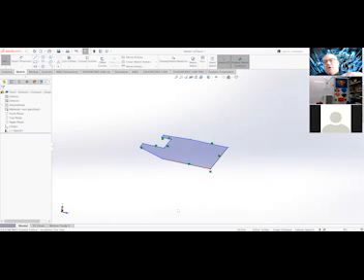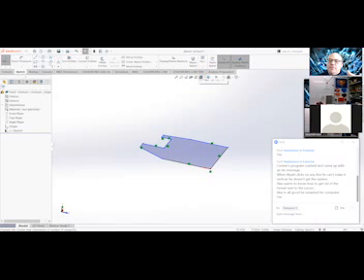So fixing your drawing is one of those things that we don't anticipate needing to do until we need to do it. And this is a good time to figure out how to troubleshoot. All right, so we're going to go up here to the view orientation cube, and if you don't know which one they are, if you just float over, just like in AutoCAD, you get a little help tag that flies out so you can see what the commands are. You want view orientation, and you want to hit the down arrow. Okay, now in here, there's a cube, and I don't use the cube because it's a little confusing. Let me show you what that looks like.